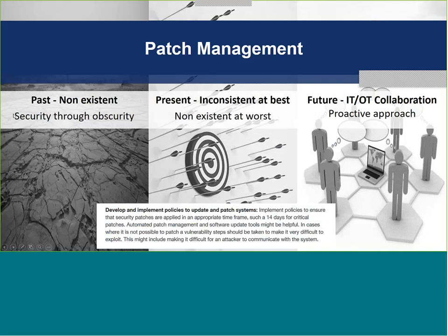When talking about patch management, control systems of the past have gotten away with not patching their OS or application. This is down to a lack of IT influence, rightly or wrongly, along with the isolated nature of the system, as viruses were less likely. There was also the topic of whether the control system would be able to take the patch and the worry that it would cause adverse effects. We have all heard of the phrase, if it ain't broke, don't fix it. For this reason, patch management was therefore near non-existent.